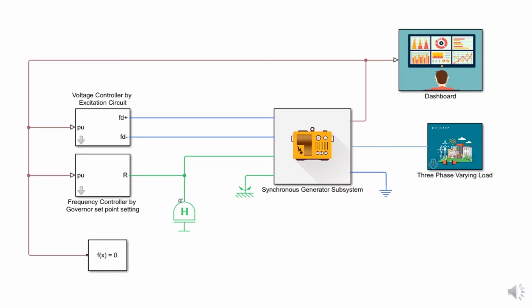The idea is to use Simulink built-in models to regulate steady-state operation of a synchronous generator which is connected to a time variable load. Here, regulation implies to monitor parameters and use them in feedback systems to control the governor set points and other operating parameters of the synchronous generator up to desirable limits within normal rating values.